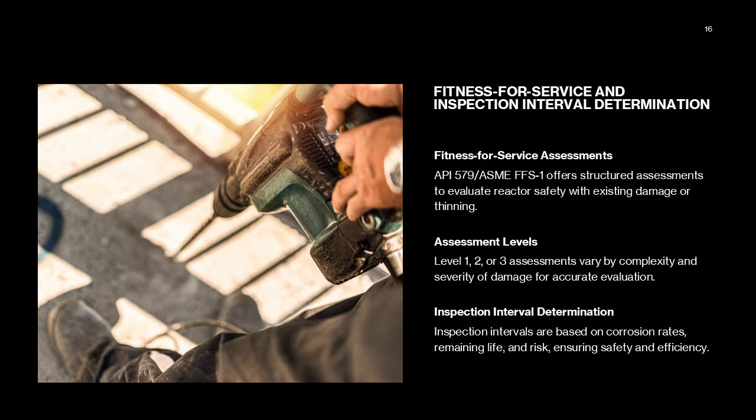When damage exceeds the direct acceptance limits of API 510, fitness for service assessments in accordance with API 579/ASME FFS-1 may be required. These assessments provide a structured methodology to evaluate whether a reactor can continue operating safely with known flaws or thinning. Depending on the complexity and severity of the damage, Level 1, Level 2, or Level 3 assessments may be performed.